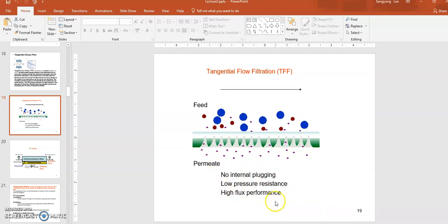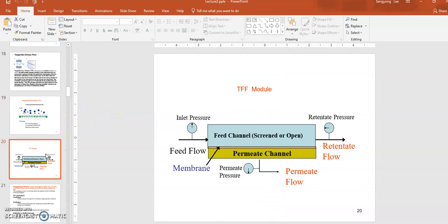These are all the benefits of using tangential flow filtration. So if you look at the tangential flow filtration filter design, it looks like this. There's a filter inside a cassette, and the main flow takes place parallel to it. The initial material comes in, goes sideways, and goes out. You circulate over and over, and there is some residual filtration happening. So you will capture, you'll permeate what's filtered through your membrane from the sideway.